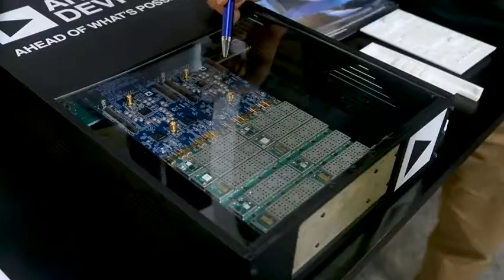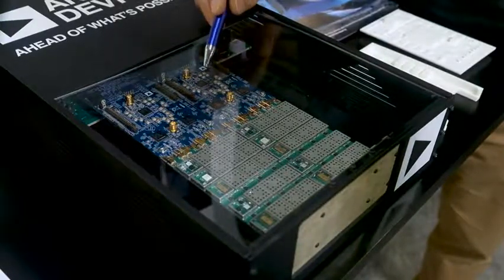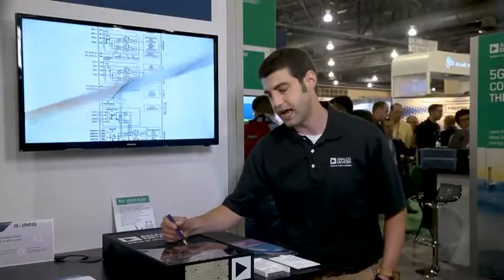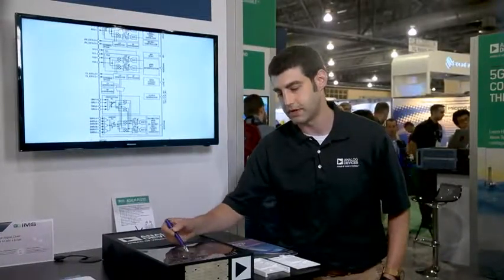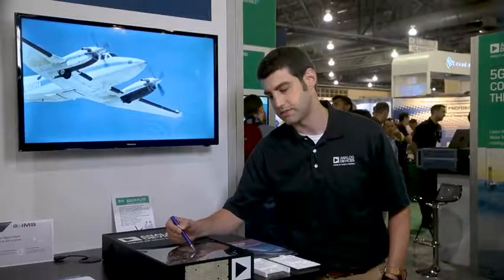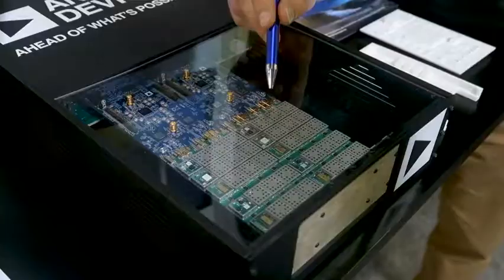Using all of these features, we're able to then build an L and S band solution if you need to stop there. If you need an X band or KU band solution, then you can use this type of up-down converter block architecture, which has mixers and amplifiers and filters. Finally, using our also newly released ADAR1000 core chip, we're able to take these 1 to 4 outputs and then go through these TR modules to ultimately get to our phased array.